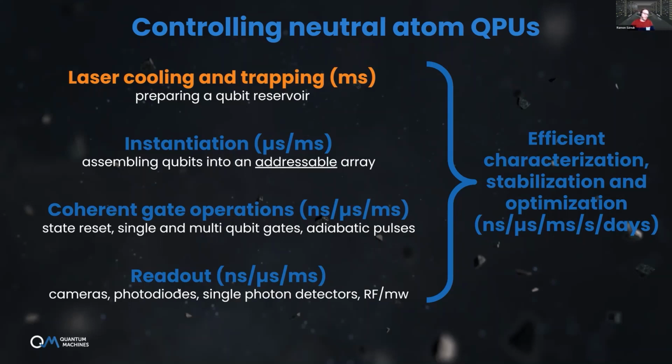And readout parameters as well. If you're doing acquisition with photodiodes, you could think about acquiring the whole photodiode trace and doing some optimal demodulation or analysis of the signal, instead of just looking at the value that the photodiode arrives at after saturating to some threshold, which is what is typically done in many cases today.